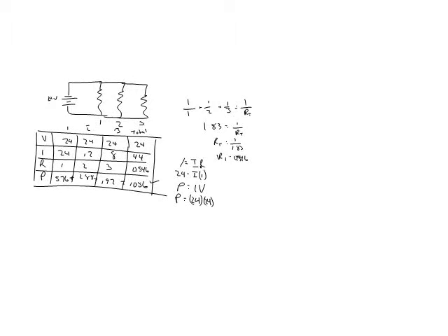So when you add them up, the current here and the current here, it should equal the current coming into the circuit. So the junction rule says that if this is I1, this is I2, and this is I3, then I1 should equal I2 plus I3. That's the junction rule. That's the easy one.